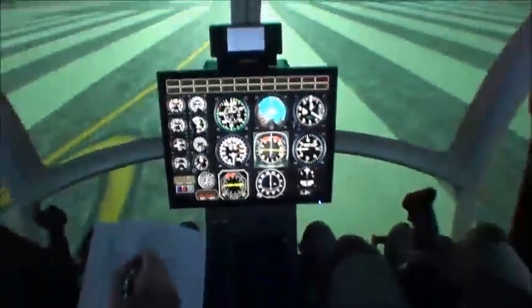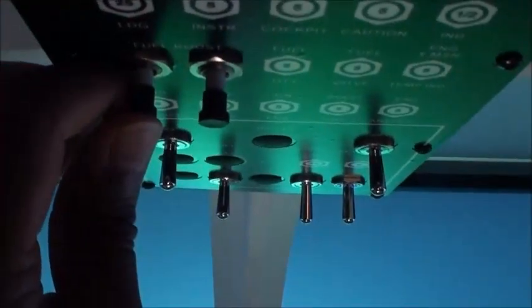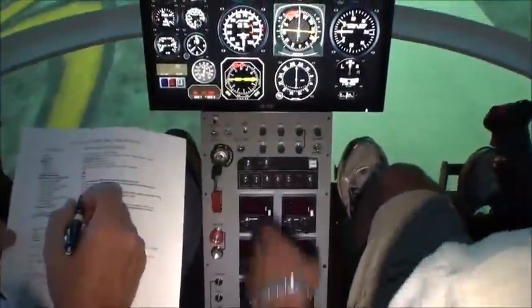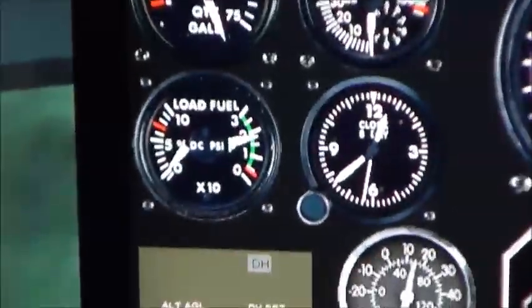Landing light, off. Landing light off, check. Overhead switches off. Switches are off, check. Battery switch on. Battery switch on, check. Fuel boost pump breakers in. So one fuel pump breaker in, check. Okay, fuel valve switch on. Fuel valve switch is on. Fuel pressure, check within limits. Got pressure on breaker 1, and I've got pressure on breaker 2, check. Okay. Fuel quantity, check.